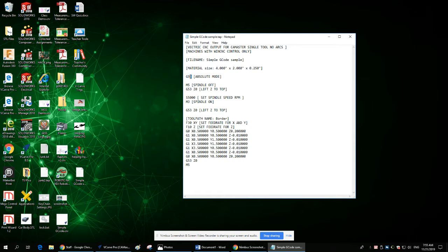Here's my first G code. I'm not an expert at G code, but G90 resets the computer to start in the 0th position. As this G code programming language grew, they started adding other codes other than G's. One of those are M codes. M5 turns off the spindle, just to make sure the motor starts off, for safety. M3 will turn it back on again.